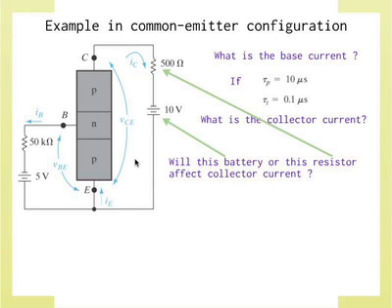This thing, irrespective of what I put in here, I can put what I want. This is essentially a current controlled current source. My collector current, the only thing it depends upon is the base current. Of course, base current depends upon the circuit on the other side, but okay. In the ideal case, it is a current controlled constant current source with infinite impedance.